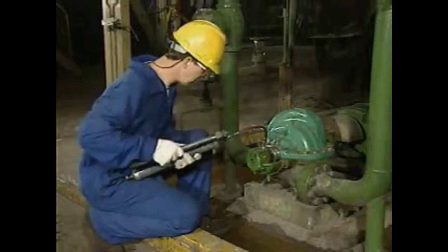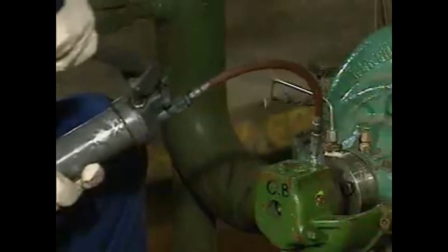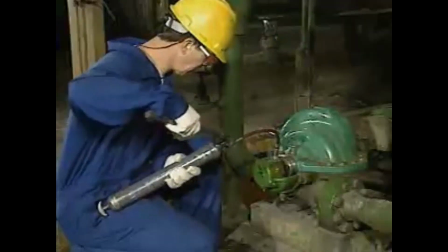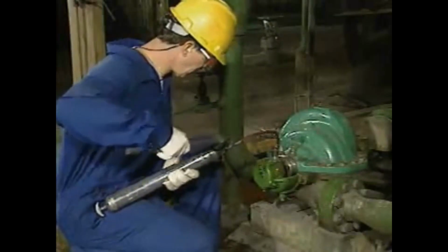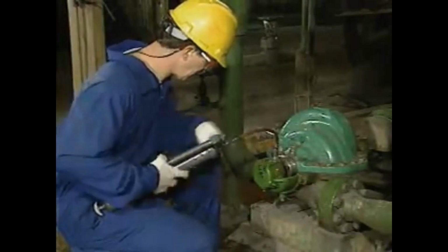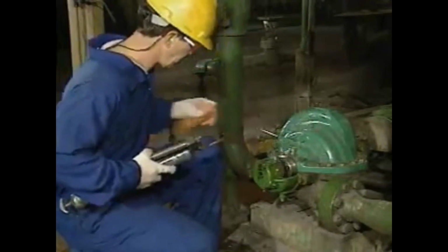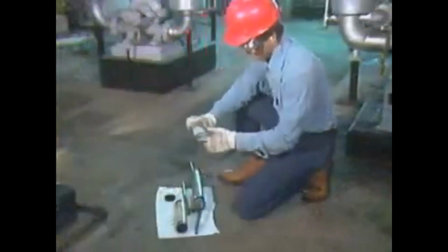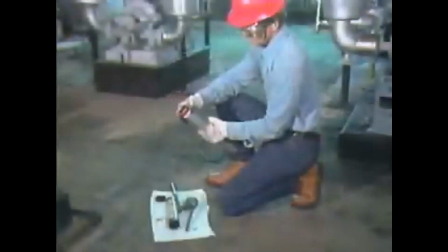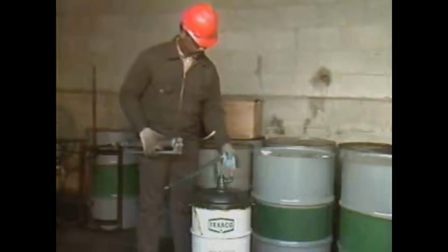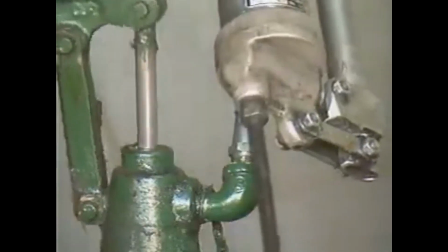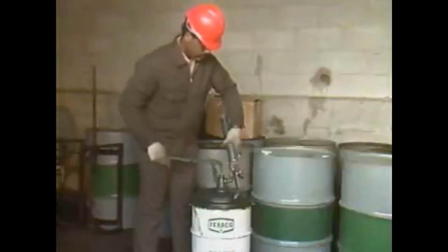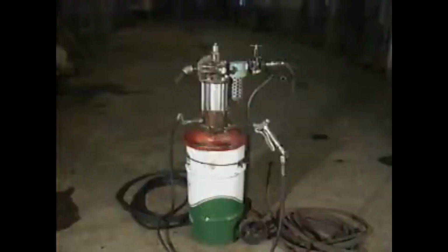Grease guns enable you to develop high pumping pressure with little effort. In fact, grease guns can develop pressures in excess of 10,000 psi, which can damage seals. So you must operate grease guns with care. A very common way of filling some hand-operated grease guns is simply to slip a cartridge of grease into the barrel of the gun. Other types of grease guns can be filled quickly and easily with a filler pump that's clamped onto a bulk grease container, then attached to the gun.